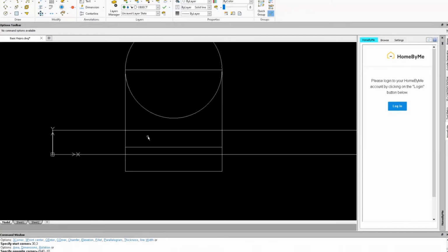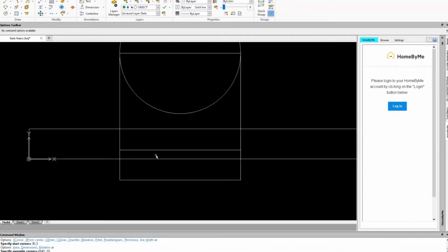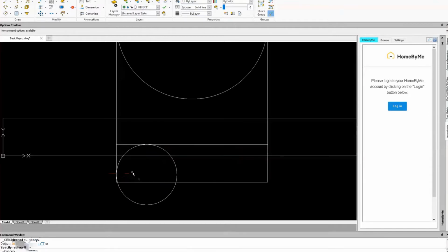So the problem I had before is when I tried to use the fillet tool inside DraftSight, sorry, I use SolidWorks all the time. But inside DraftSight, using the fillet tool for this particular object here, I needed an 8mm fillet. And because this one line here from here to here was so short, it wouldn't let me create a fillet. So I'm going to have to work around that. So I'm going to use the circle tool to do that, and I'm going to use a tangent radius circle with the 8mm radius. So I'm going to put that circle right there in that corner.